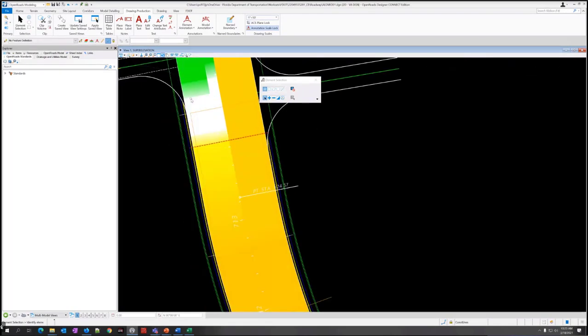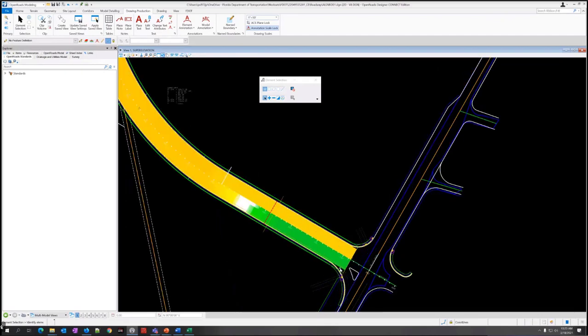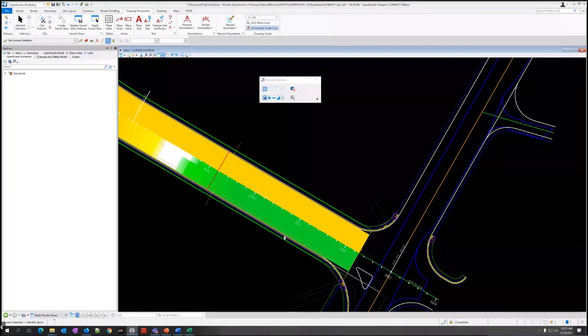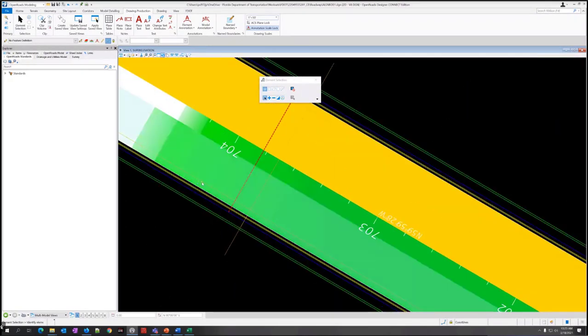Remember this model, it generated automatically, so it's not in there. If I had the curb in there, it would have actually generated the lane for it. So you wouldn't have to do these extra steps just because of the way we split it. There's a few extra steps. So we're going to have to create that.